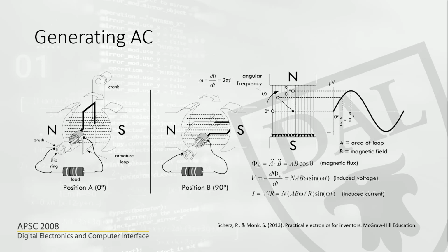So that can be power produced in power plants. The way we produce power in power plants is we use coal or nuclear reaction or something like that to produce heat. The heat heats up the water. The water is converted into steam. That steam is used to spin a turbine. The turbine has a shaft, and the shaft will be connected to a generator like this. And as the turbine rotates, the rotor of the generator will also rotate, and that's how we produce it. So that is the thermal power plant.